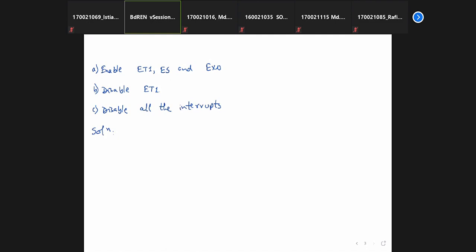Okay, how about ID 1061? Tanmay. ID 1061, can you hear me? Yes, sir. Alright. So the first one, the question is, we need to enable these 3 interrupts, ET1, ES, and EX0. So definitely your instruction will be something like this: MOV IE, hashtag.